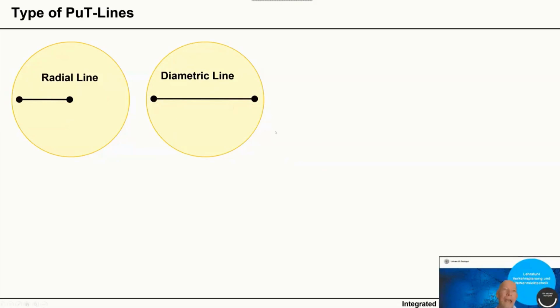A diametric line is usually more favorable because you don't stop in the city center. In the city center, especially with buses, space is valuable. You don't want to have a big bus station, at least not for your urban transport, maybe for your regional transport. And people's destination is not just in the city center. Maybe the destination is a little bit behind the city center. So with this system, you provide more direct services.